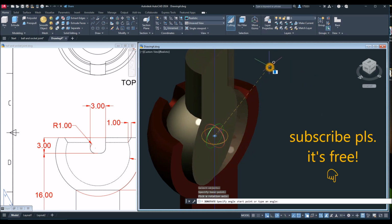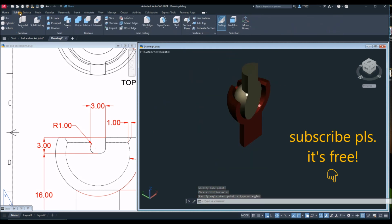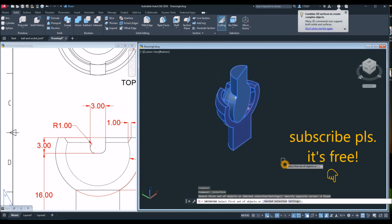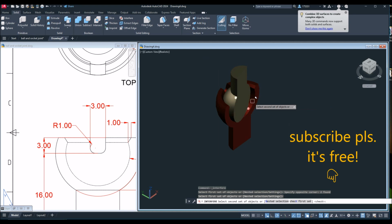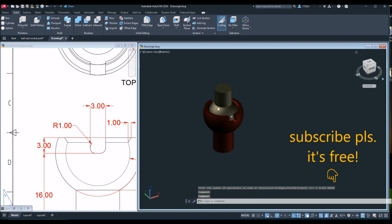I'm just gonna try that and then select interfere command inside the solid editing panel and just window this one and then enter again. And again, it says here, objects do not interfere. So we're good.